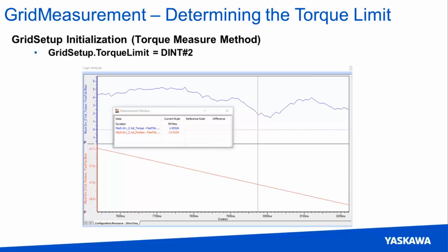At this point where my cursor is located, that is where the machine was touching the bed. You can see it was hovering between 3 and 5, and then once it started touching the bed, the torque hit 2 and briefly paused, took the measurement, and started its move back up after restoring its original torque.